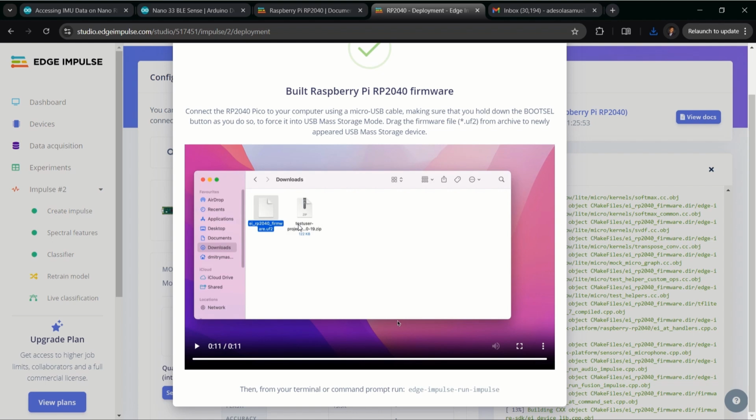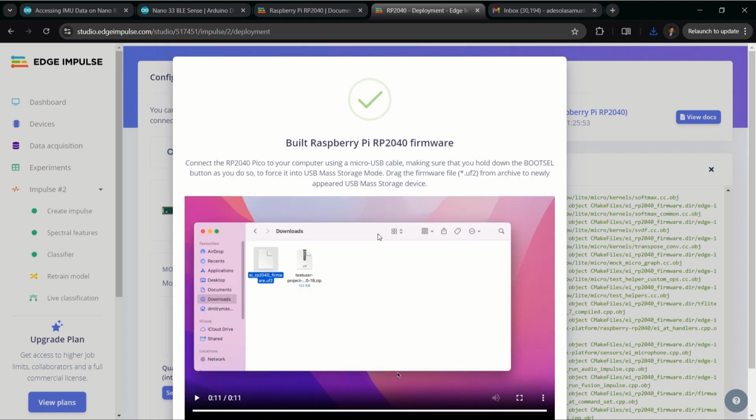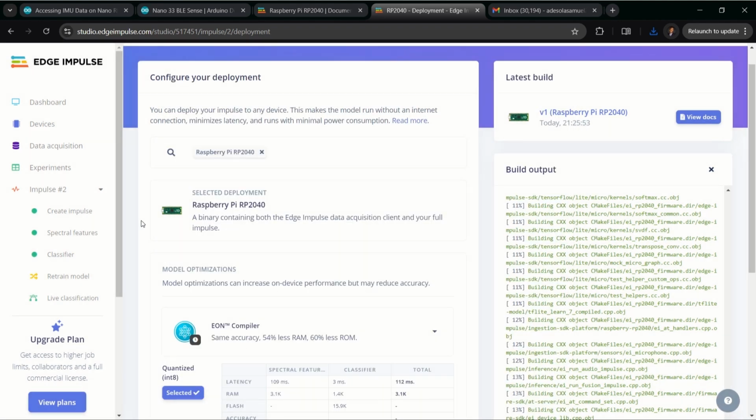But one thing I also want to show you is that I'm going to compile this for a normal Arduino, because I want to be able to tweak some of the parameters there and use that to control my device. It's not that easy for me to change a .uf2 file. So I need to compile again for normal Arduino, upload it using the normal Arduino method, and edit some parameters in the code and then upload it so that I'm able to use it to control my device.